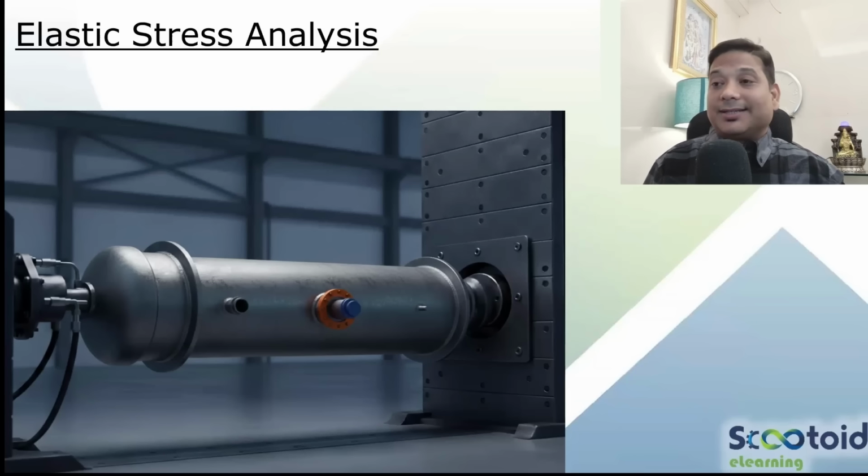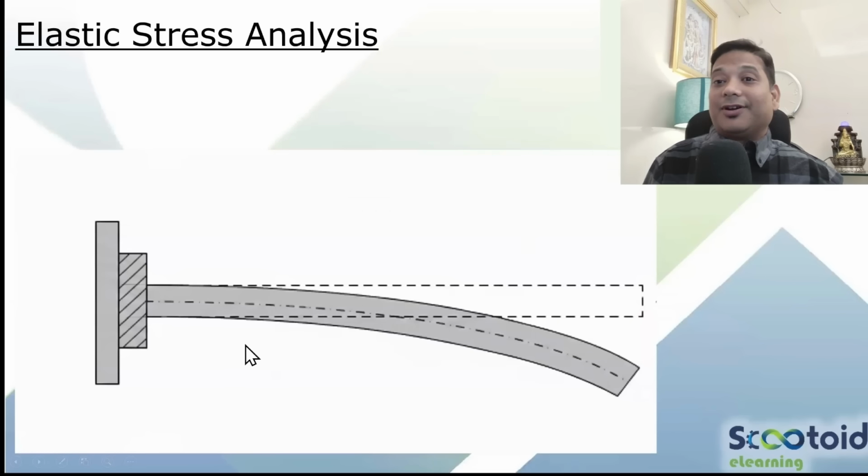You can do the analysis, but in the post-processing part, where we classify these loads as primary membrane, primary bending, local, secondary, there you need the expertise. If you go wrong there, your complete analysis will be wrong. So post-processing is very important for these kinds of analysis.